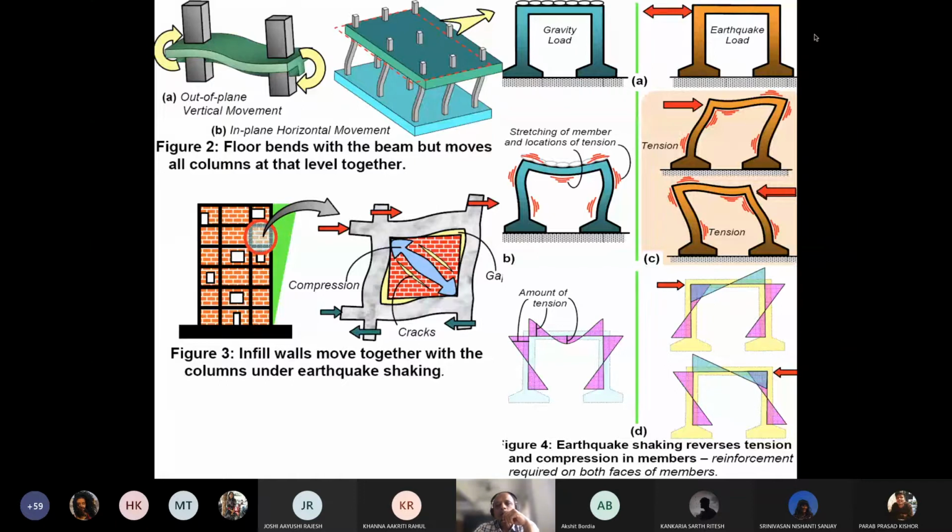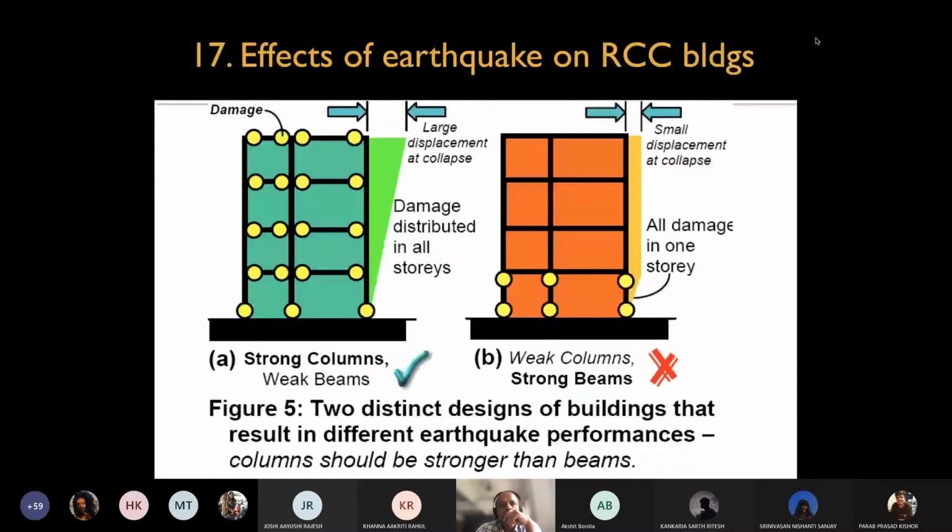At one instance, the stresses are maximum not only at the junction but even at the base. At another instance, it goes in the completely opposite direction, to the other end of the spectrum. So it is important to understand these corners, whether we want to make them stiff corners or flexible corners, the joineries between the column and beams. That becomes very important, and this diagram helps in understanding what approaches one can take while designing this.